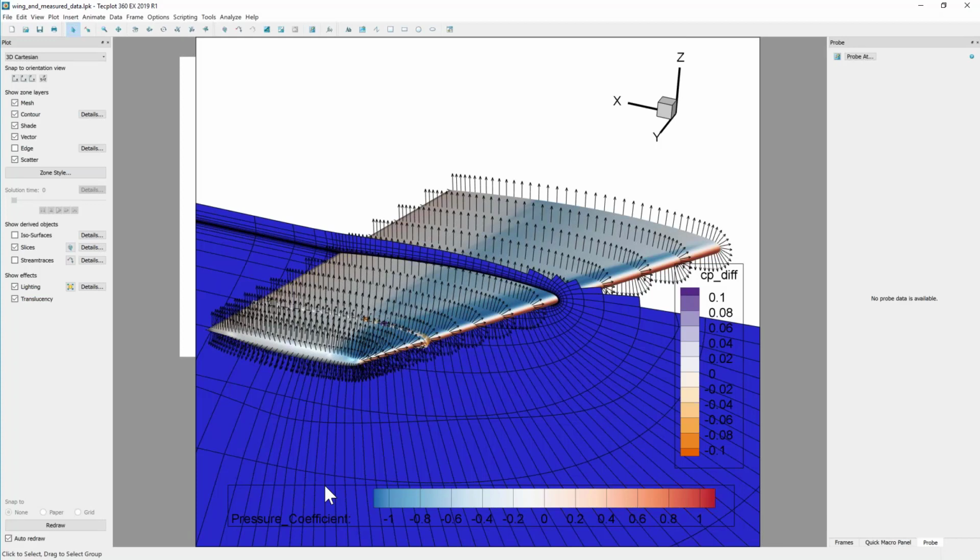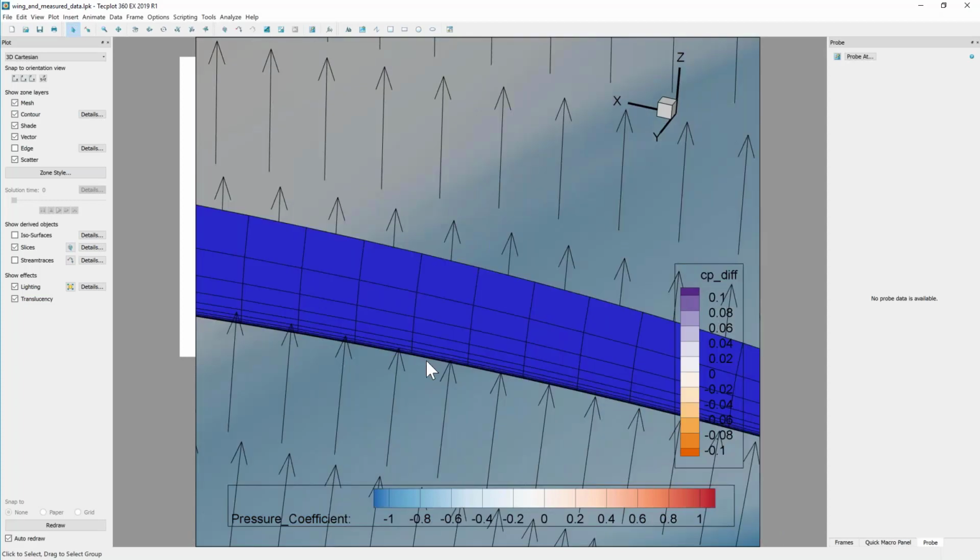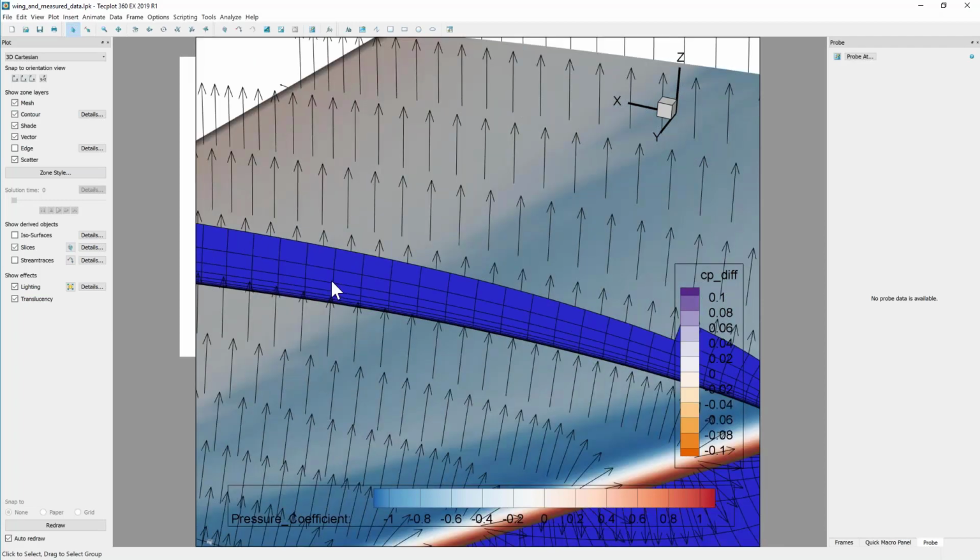How do I plot a velocity profile over a line in the way that the journal articles show? Again, I think the way to do the velocity profile would be a slice of a slice, because that way you'll have a line that goes right along each one of these cells, and then you could plot the velocity values along that line. Doing a slice of a slice and trimmed would get you there. You could also couple this with the technique of computing the surface normal. Slice of a slice is one way, but that's not going to be exactly normal to the surface. So you could create a line that is normal once you've calculated those normals. Again, I think we can help you out with that.